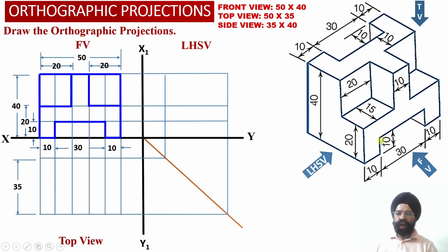So we are going to observe the true shape projection of this Y-shaped web into the front view projections over here. Corresponding to this rectangular slot, we are going to observe the true shape projection of the rectangular slot into the front view projections over here, because once again this open surface is parallel to the vertical plane. Then again we have got two surfaces over here.